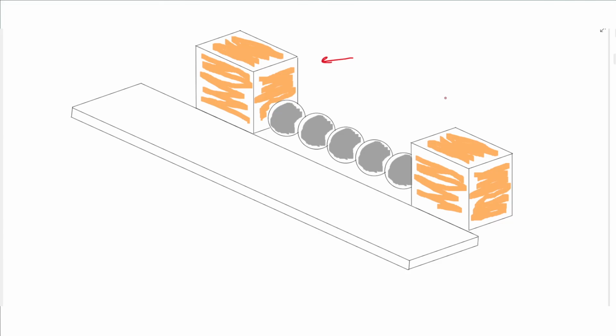These questions could be asked in paper 4 or paper 6, so you can use it in both papers. Say you want to measure the diameter of one ball bearing, but you have identical ball bearings. You can place them right next to each other and measure the total length, looking perpendicular to the scale, and then subtract the two readings to get the length of all the ball bearings. Then you divide by the number of bearings.